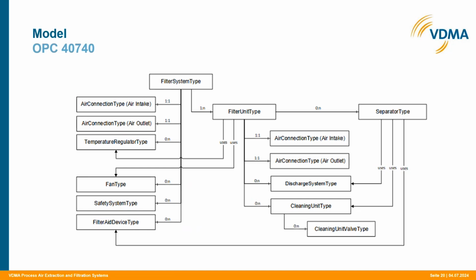And the cleaning system is the system I just talked about that removes the dust, the accumulated contaminants from the separator, and each cleaning unit may also have valves that are used, for example, for pressurized air to clean the dust off this separator.